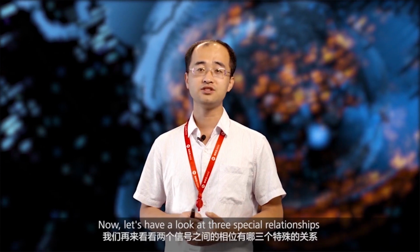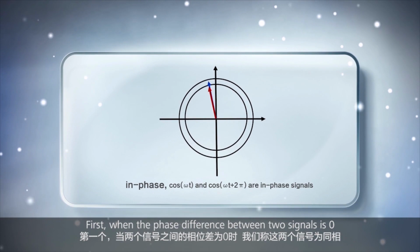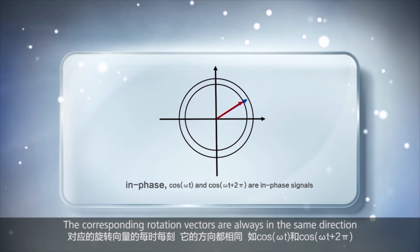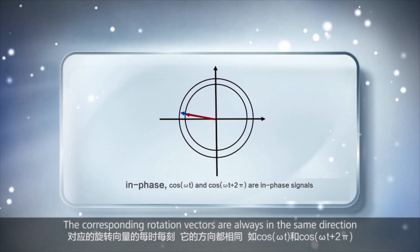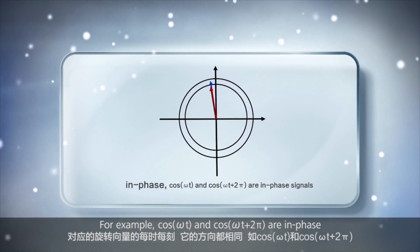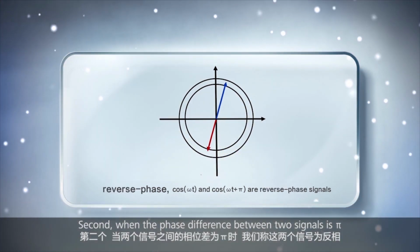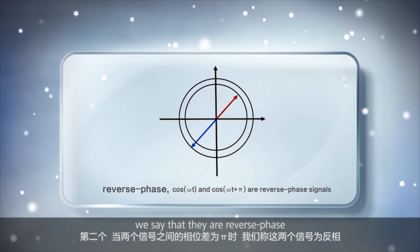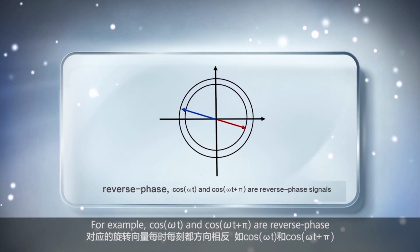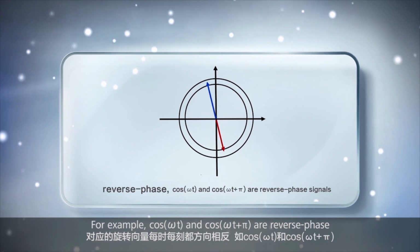Now let's have a look at three special relationships between the phases of two signals. First, when the phase difference between two signals is 0, we say that they are in phase. The corresponding rotation vectors are always in the same direction. For example, cosine omega t and cosine omega t plus 2 pi are in phase. Second, when the phase difference between two signals is pi, we say that they are reverse phase and rotation vectors of each signal are in opposite directions. For example, cosine omega t and cosine omega t plus pi are reverse phase.